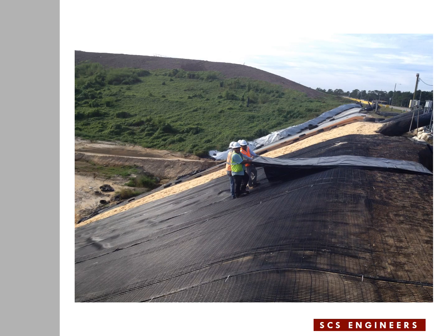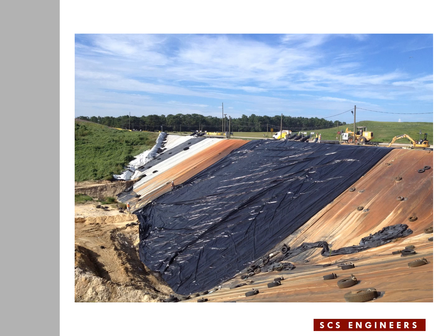Then, since this cell is not going to be placed in active mode or operation, they're going to cover the geogrid with a plastic sheeting like other areas, other slopes, and secure the plastic sheeting. This is the plastic sheeting over the repair area, and then they would add a ballast load on top of it in order to keep it in place. After completing the plastic sheeting and securing it, the project gets pretty much completed.